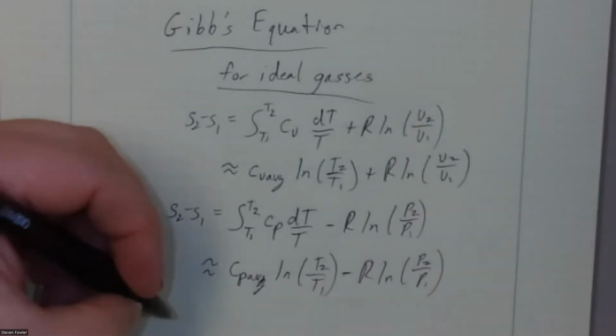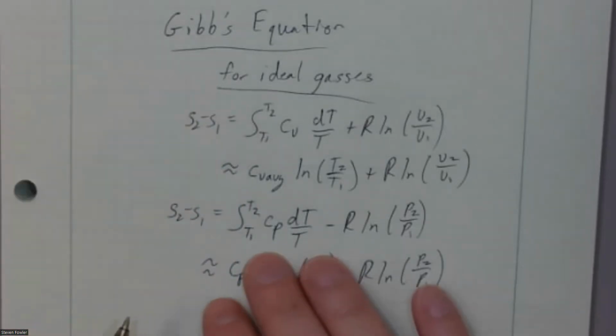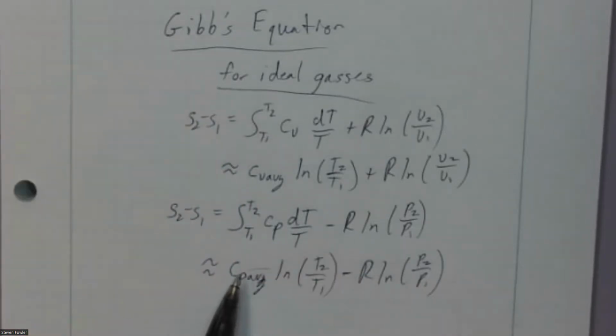What else here? And we did say that if you don't like, again, to use C sub P, we've seen this earlier. To use C sub P average, that means I need to know both temperatures. If I don't know both temperatures, I'm going to have to guess and check. I'm going to do a quick iteration to get down to using basically the table as my equation relating C sub P to T2. It's going to require a guess and check.